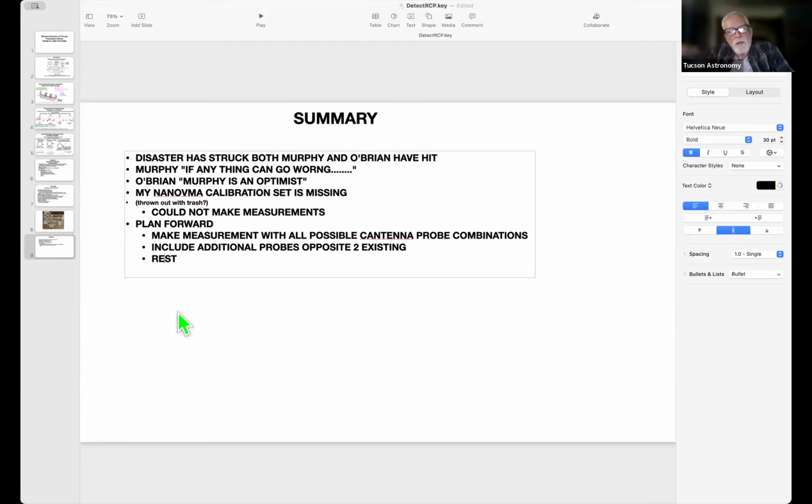So you've got the VNA generating the signal. What's your detector? The detector is the other port. There's two ports on the VNA, port one and port two. Port one is what you're using for generating. Port two is what you're receiving with. That's how you detect your through signal.